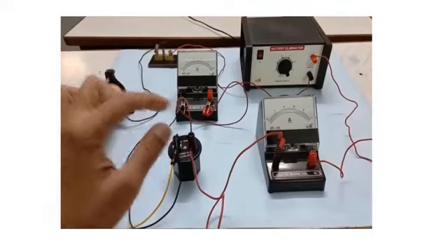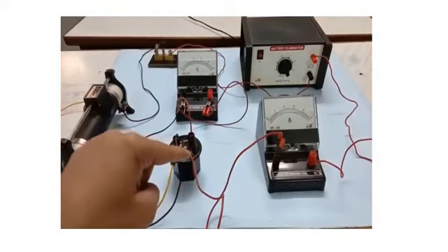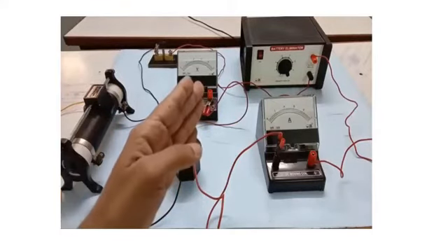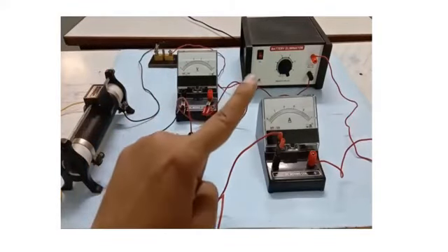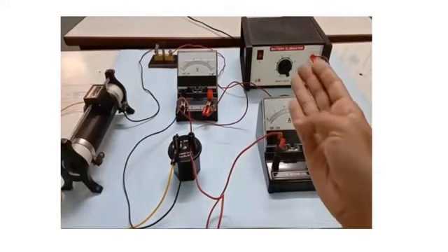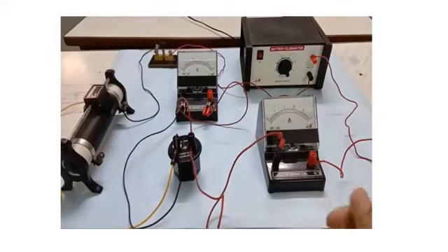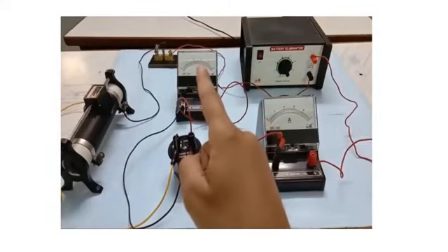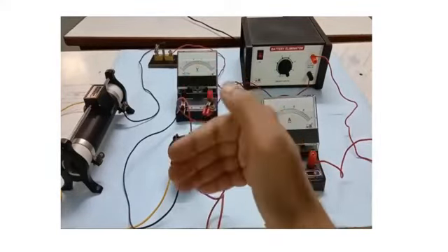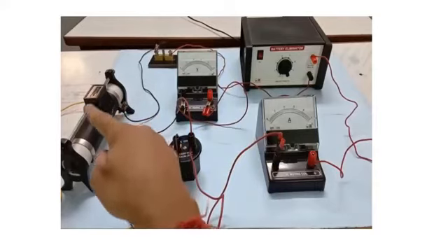Before switching on the power supply, you have to study the scale of this. So when you study the scale, what will happen? If one division measures one particular value, when the needle is coming to 5 division or 4 division, then that value of one division into the number of divisions shown by the needle will be the reading which is given by the instrument. So slightly we have to move this rheostat, that part also you take care. So the readings similarly in the voltmeter as well as the ammeter, we have to tabulate in a tabular column also.